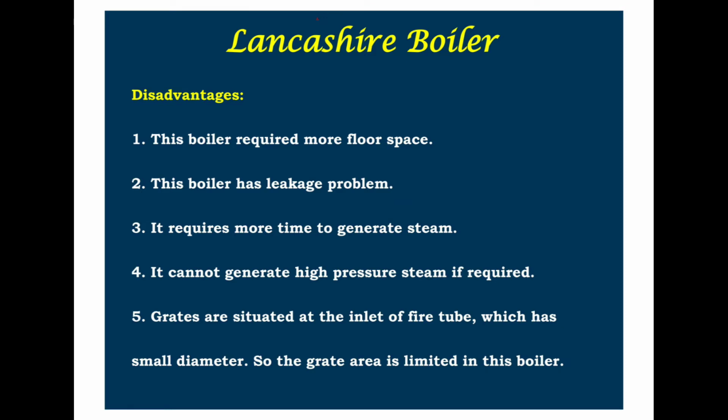The major disadvantages of the Lancashire boiler: it requires more floor space. This boiler has leakage problems. It requires more time to generate steam. It cannot generate high pressure steam if required. Grates are situated at the inlet of the fire tube, which has a small diameter, so the grate area is limited in this boiler.